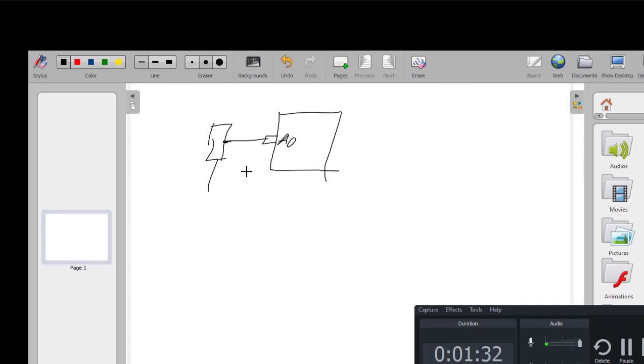Now I'm going to explain why in this case I'm choosing an analog port to do pulse width modulation. This potentiometer, which is connected to the ground, we are going to be reading the analog voltages. Of course, we're going to input analog voltages to the potentiometer, but then the A0, we all know from the theory of ADC, will be spitting back to us the digital value.